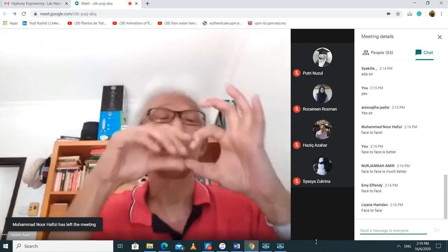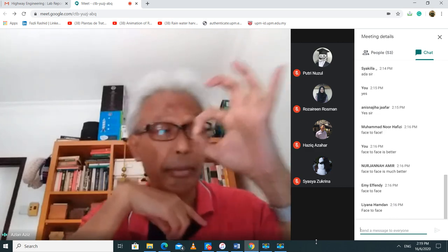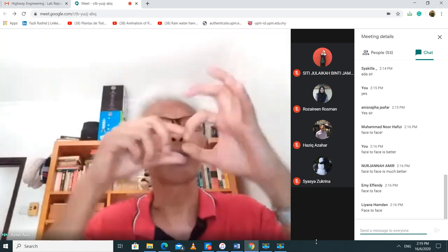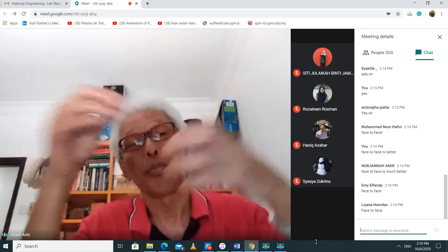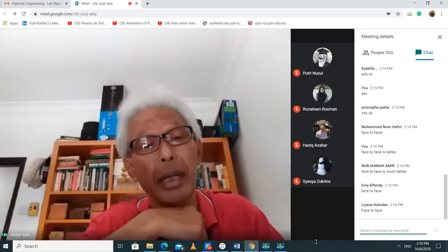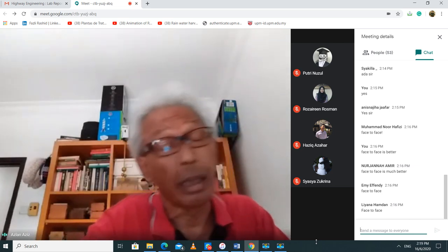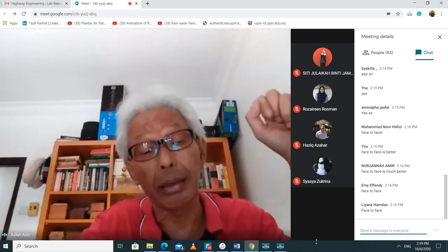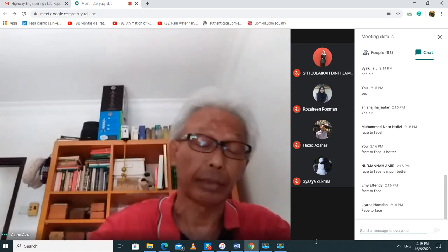It's one in which you have a ring about that diameter, which is about maybe 2 inches. 2 inches is 50 millimeters, and you have it about this thickness, and you put clay in it, and then you load it in the soil mechanics lab, right? And then you come back every so often to collect the data for the settlement, all right? Obviously, it's all under saturated condition. If you recall your soil mechanics lab, all right?